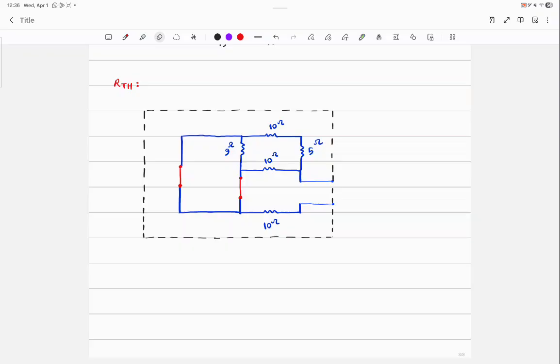Let's suppose that you are required to do this in your lab, in your mini lab. What would you do to measure resistance? So it's not open. It's connected to a multimeter, okay? Now, because you have the tendency to forget that, I'm asking you to do this. Draw it. And write a multimeter here. So you know that this is actually connected to a multimeter. And we want to measure RTH from across these terminals.